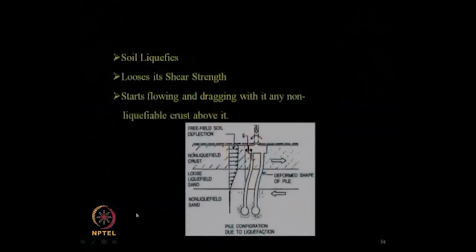So, this kinematic interaction along with the inertial interaction needs to be considered combinedly to get the combined effect of this earthquake forces on the pile foundation, and in the design we need to consider both the aspects of kinematic as well as the inertial loading conditions in the design of pile foundation. So, let us look at this picture once again.